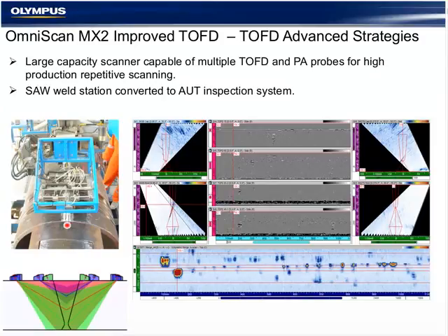This is upcoming. Previous generation modules can be converted now using a TomoView display like you see here, where the TOFD displays, phased array zones, sector scans, and phased array merged C-scans can be customized and rearranged as necessary.